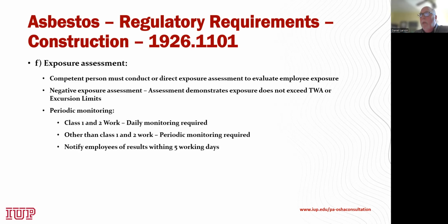There's a requirement to perform an exposure assessment, and that must be conducted by a competent person to evaluate what the employee exposures are. A negative exposure assessment is an assessment where air monitoring is performed to determine what the employee exposures are. It's considered a negative exposure assessment if the exposures are actually less than the TWA or excursion limits set forth by OSHA.